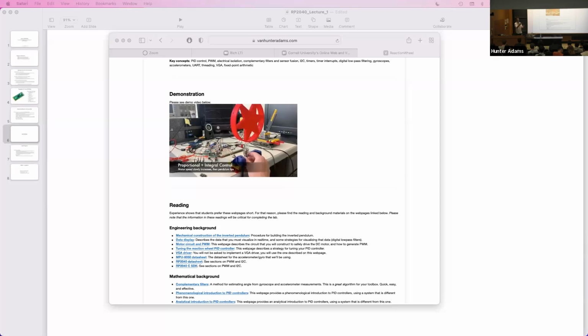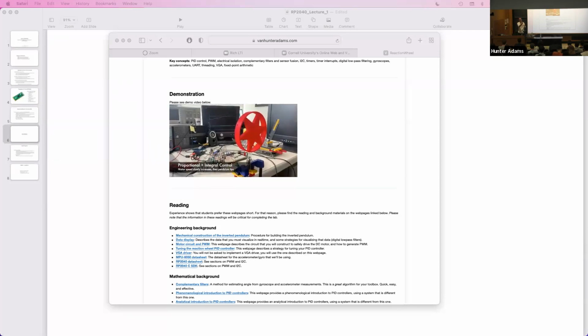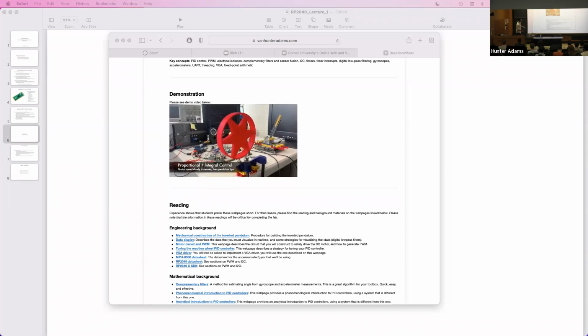It can also excite modes in the spacecraft so that the whole thing starts kind of wiggling, which, if you have sensitive optics pointing at some distant place, you don't want to happen. So the solution instead is to use momentum control devices.